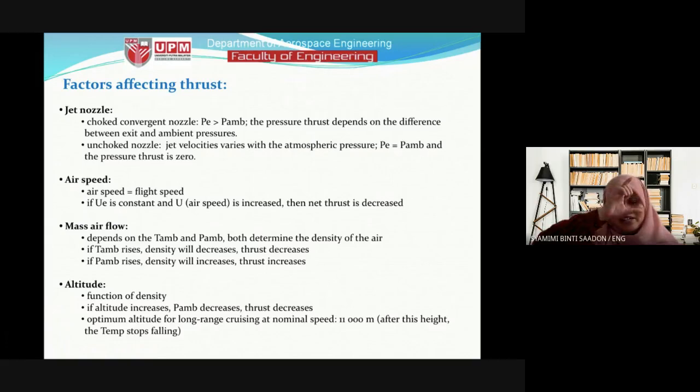The first part is the convergent part, up to the throat, which is choked or unchoked at that location. Normally in a Venturi or convergent nozzle, we try to reduce the back pressure, so that the air is allowed to flow into the Venturi.